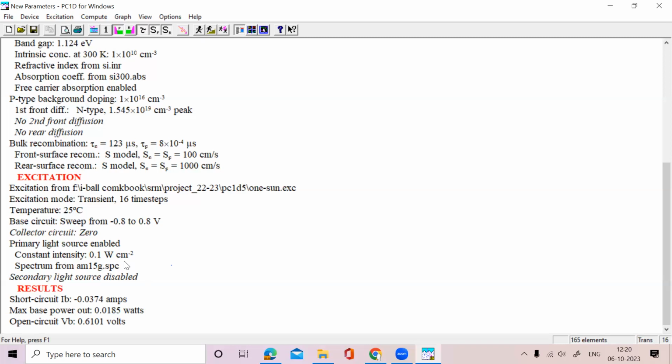Firing, heating, thermal shock. Actually, what happens? There is a tray moving with some speed. In between, we give some temperature. For a very small amount of time it goes to a very high temperature, more than 1000, and in that time it punches through the dielectric and touches the N layer. It should not touch the P layer. If it touches the P, your junction will not work.